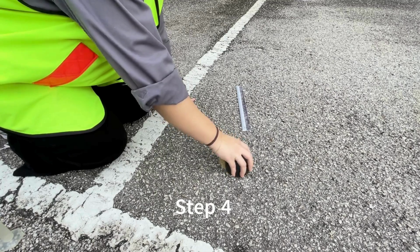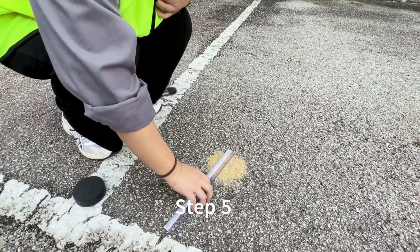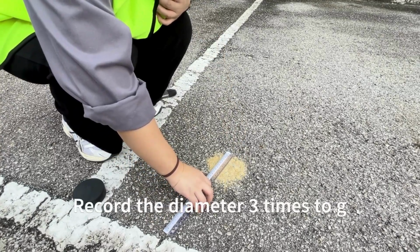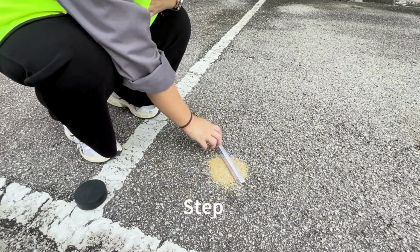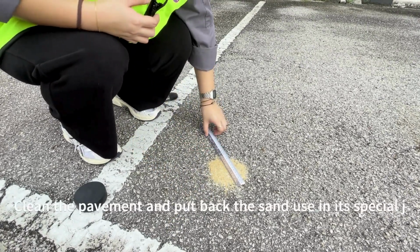Step 4. Flatten the heap of sand following counterclockwise. Step 5. Record the diameter 3 times to get the average. Step 6. Clean the pavement and put back the sand used in its special jar.